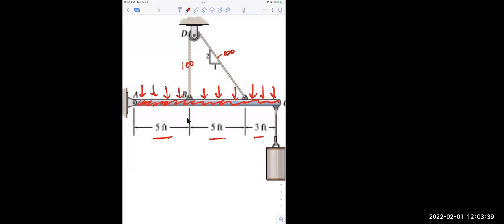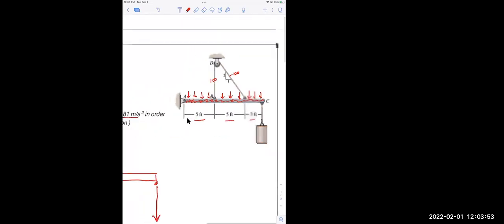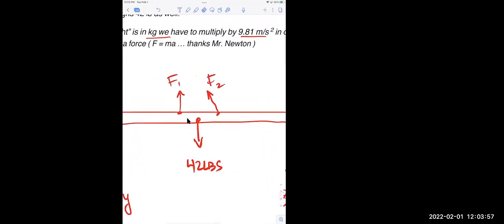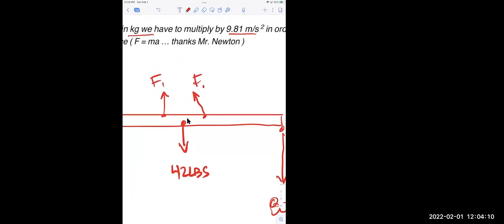So those are exactly the same. So by me differentiating them force 1 and force 2, I'm actually acting like they're different, but they're not going to be different because that's a cable going around a pulley. So those are going to equalize. That's kind of the point. Now, however much force each one has, they're going to end up the same. And so I'd be way better to label these force 1 and force 1 because they're actually the same. Now they are being pulled at an angle. Force 1 is straight up. The other force 1 is pulled at a 2-to-1 angle. Maybe I'll do a little better and draw that in. But those two forces would actually be identical. If I do put that Pythagorean theorem on 2 and 1, I get the square root of 5.